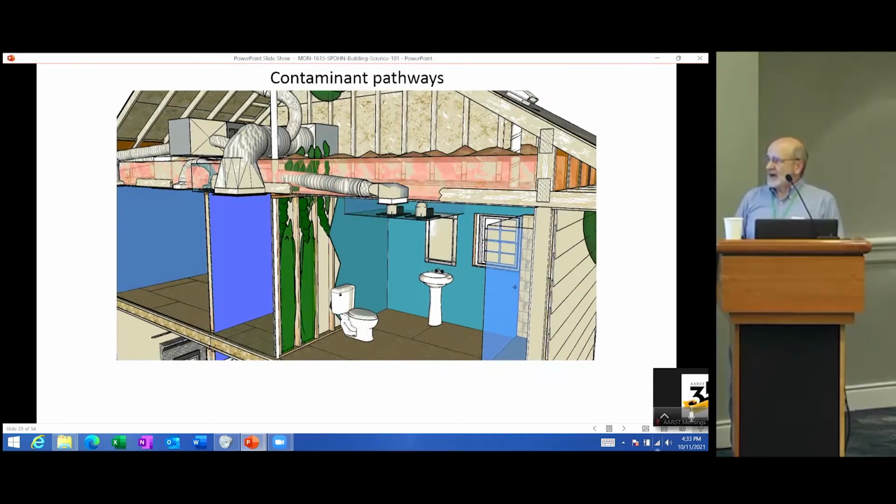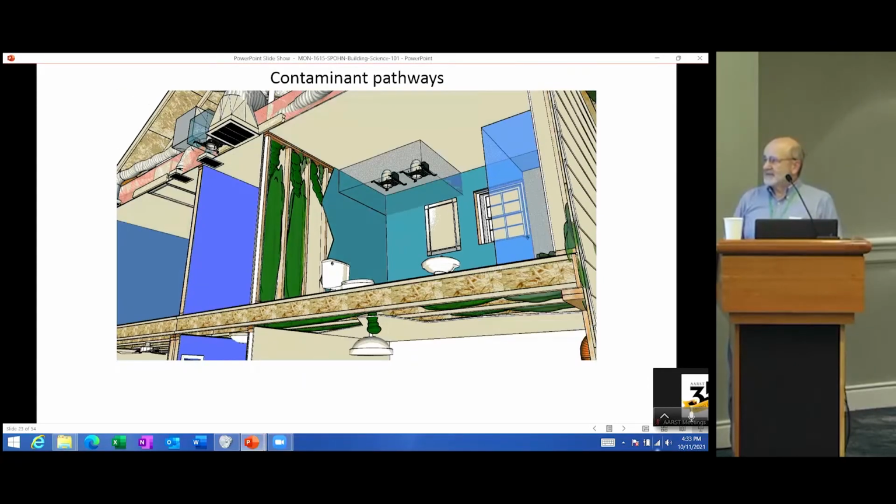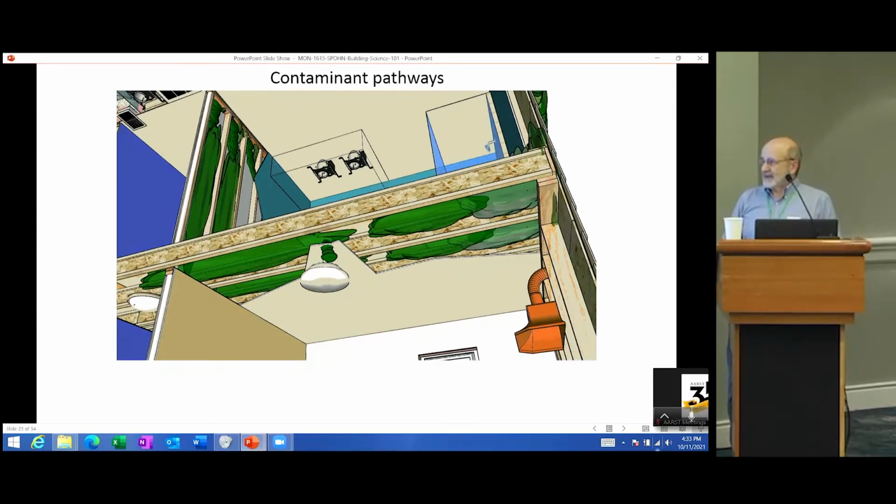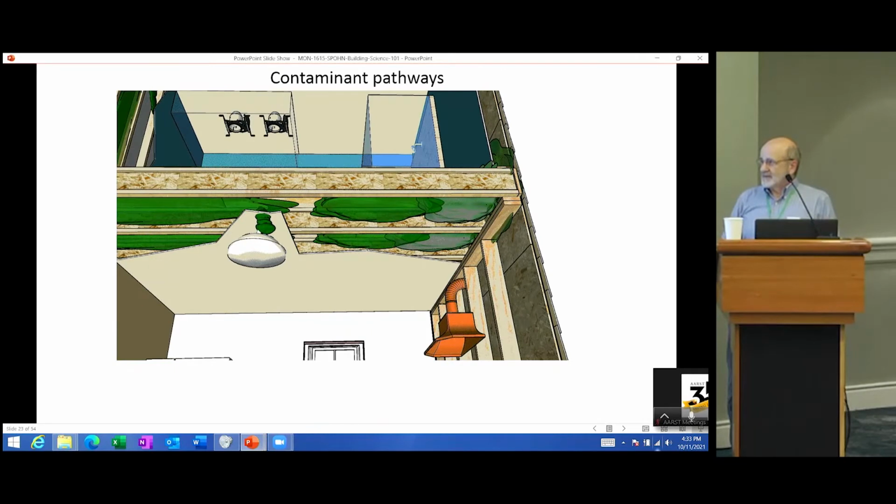And what would cause that air movement going from the second floor to the first floor? You see a large kitchen exhaust hood, which is depressurizing that space. They can run up to 100, 200 CFM, and there are some super ones that run even 400, 500, 600 CFM.